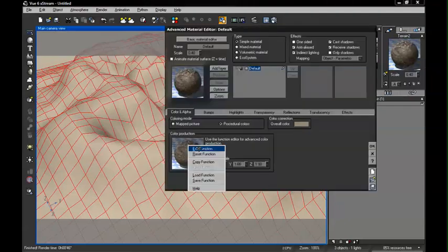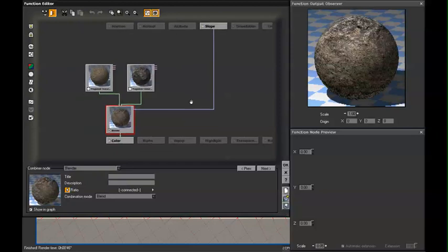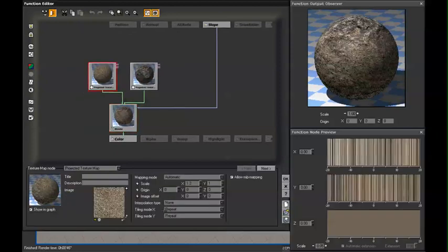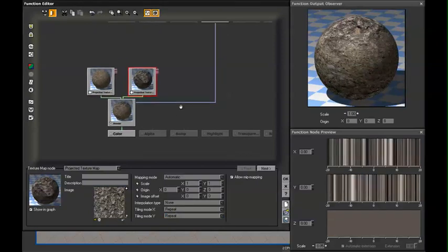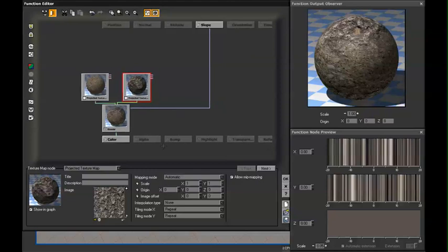We're going to open up the Advanced Material Editor and go into the function. Since we have our tiling mode set to repeat, once our current material and texture reaches the end, it's going to repeat itself. And since these are all seamless textures, that's not going to be a problem. But if you're not working with a seamless texture, then you might need to change it to the mirror mode, and even then you're going to get some undesired results. So typically, you want to work with seamless textures. The entire seamless rock collection is seamless, so it works very easily with all of this.